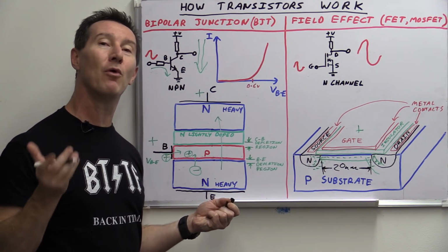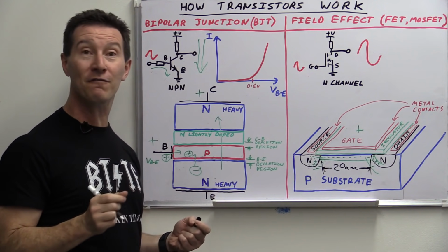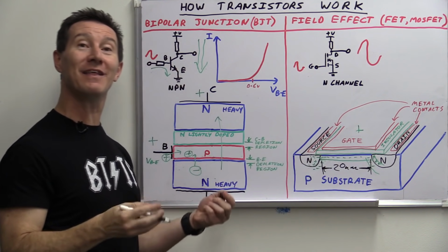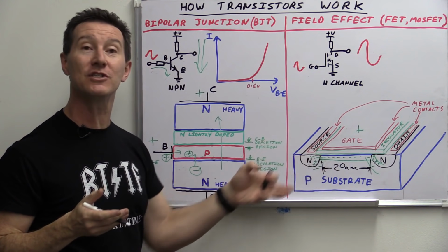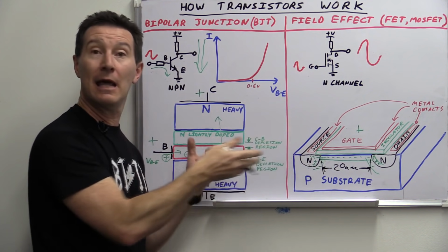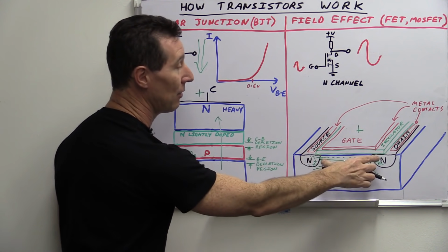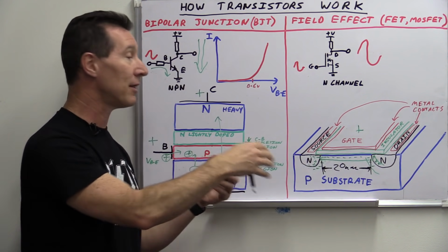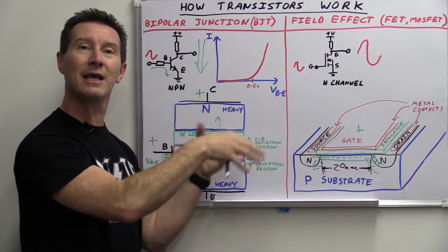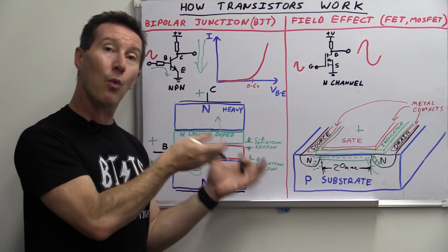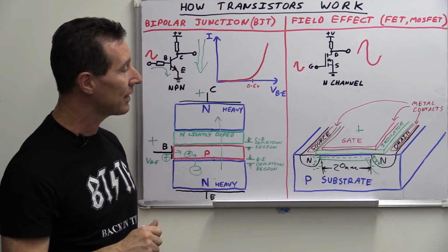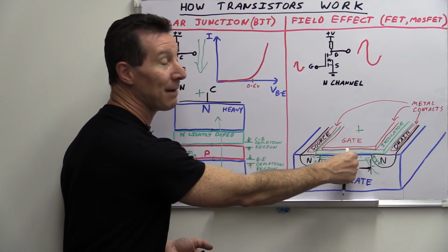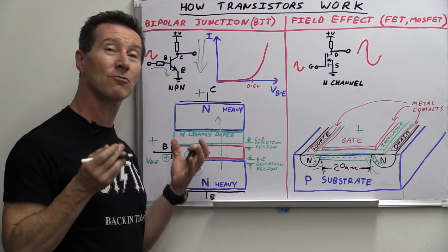What does that translate to? Well, a silicon atom is about 0.25 nanometers in diameter, effectively. So there's effectively only 80 atoms in there, wide between there. So you can see how ridiculously small feature sizes these are, and how Moore's Law, as we traditionally think of it, is pretty much coming to an end. You can't get much smaller before this doesn't become an insulator anymore. It doesn't become a barrier. The electrons will just jump across and they can tunnel through. We get to the point where quantum effects and quantum tunneling come into it. I won't go into the details of that, but yeah, we're really sort of pushing the limits of Moore's Law. We can't physically make these much smaller before we run into lots of real major problems.